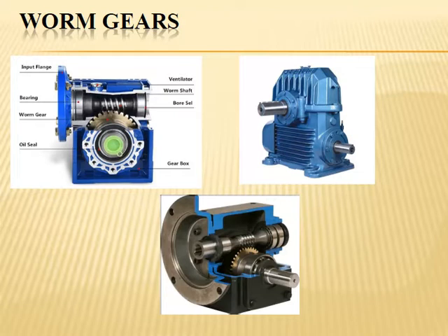So while designing the gearbox, the shape is very important. And again, to dissipate the heat generated inside the worm gearbox, we have to introduce fins. We will discuss when to introduce the fin and when to introduce a fan. But keep in mind that initially, as very huge heat dissipation is needed in a worm gearbox, we have to provide fins, and in some cases we have to provide fans for dissipating the heat.